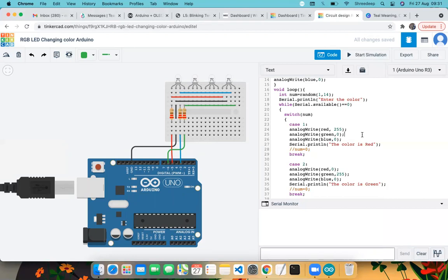Now you can have a few sections. Unless and until the user prompts something from the rotary encoder, it will keep on displaying random colors. That is up to you, but that is not my intention. The intention is that once the rotary encoder comes into action, by moving it the menu keeps moving up and down, up and down. Then once you select something by pressing the button, it will display that color, or a certain RGB. That is the task.